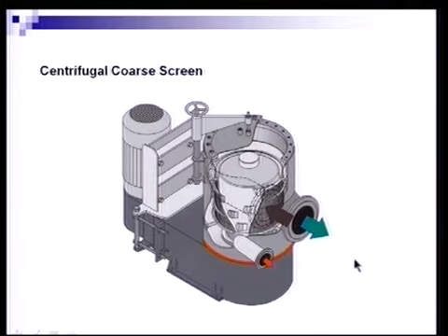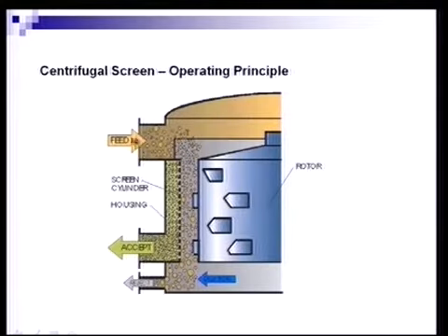Okay? I'll show you in the next graphic. This is what we're talking about. The feedstock comes in. There's typically kind of a rock trap arrangement or some sort of barrier protection to keep the nuts and bolts and the dog hairs out of there. And the stock will spill over and go between the annulus between the rotor and the screen plate. The screen plate is stationary. The rotor, of course, is driven and acts to agitate the pulp in order to mix it up to equalize the consistencies from the top to the bottom of the screen. And basically improve the screen operation.